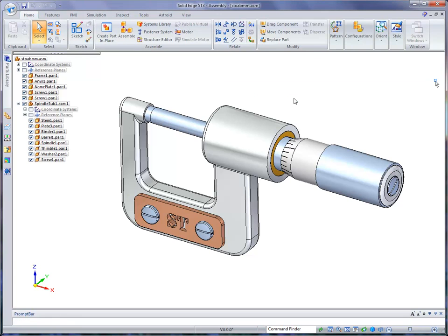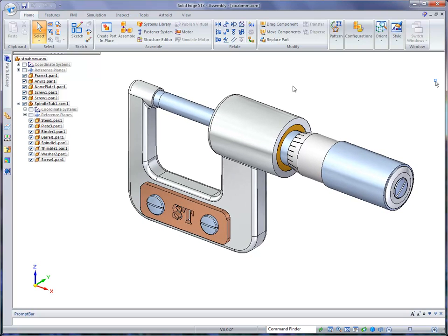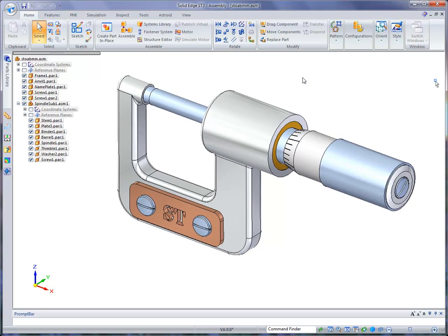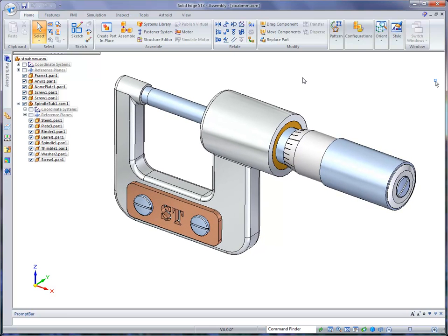So Solid Edge allows you to structure your assemblies and reflect an accurate bill of materials. You can use, of course, Property Manager, just like we did, to globally access all of the properties and add missing information or change what is directly or already there. So at this point, what you want to do is make sure that your students are able to change that material, add material property, and change it to stainless. And this concludes step 6.